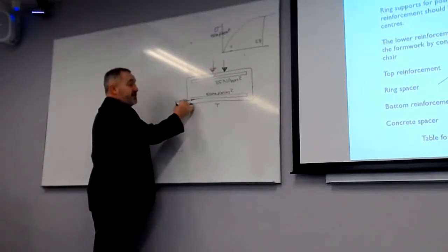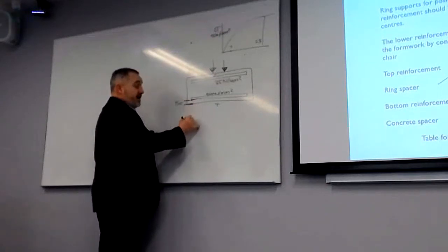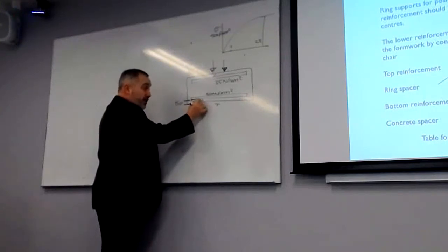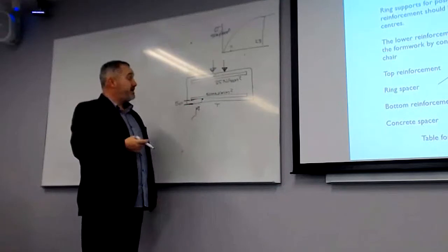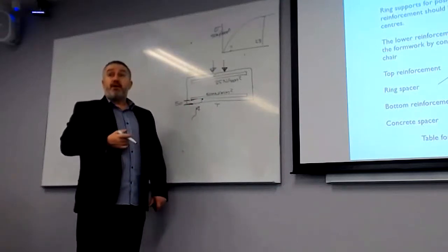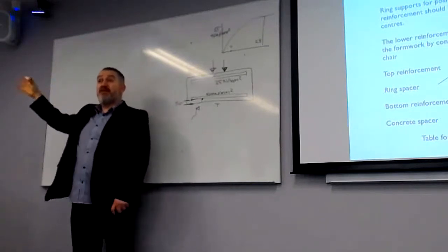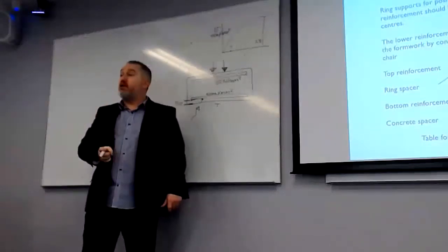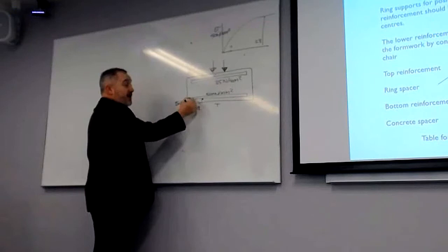And what that takes into consideration is, if it's resting on the ground, you've got all of these chemicals that could be trying to get through the concrete, and as soon as they touch the steel, they could deteriorate it. Or if you design a concrete building here compared to at the beach, at the beach you've got a lot of water and a lot of salt soaking into the concrete, so you need a larger area before you get to the steel.